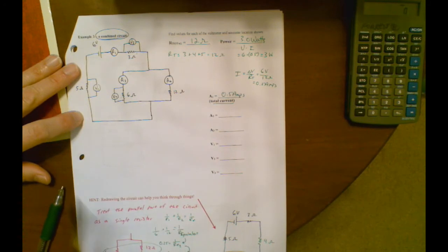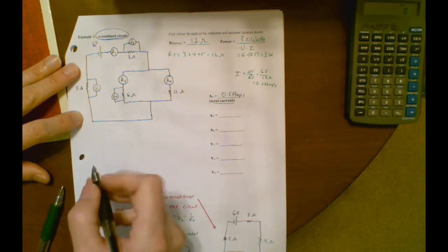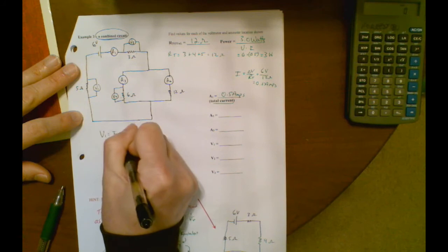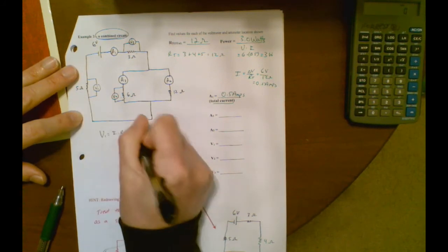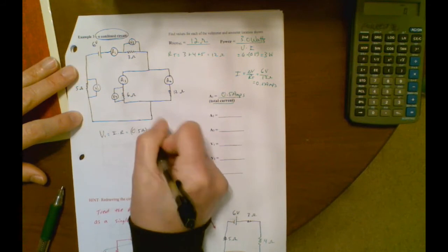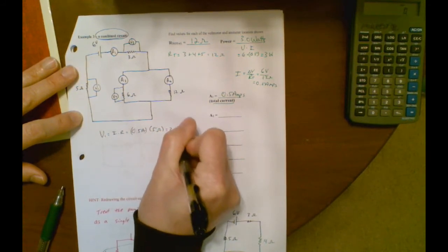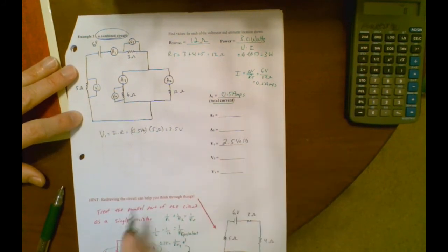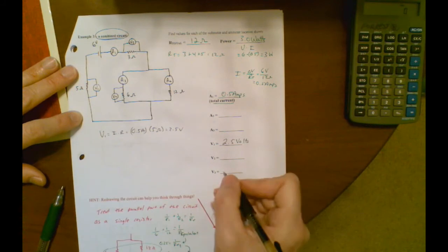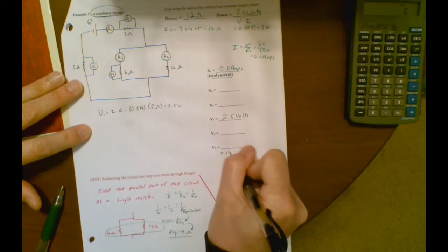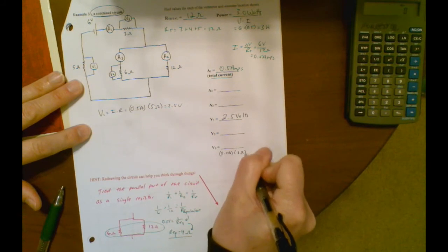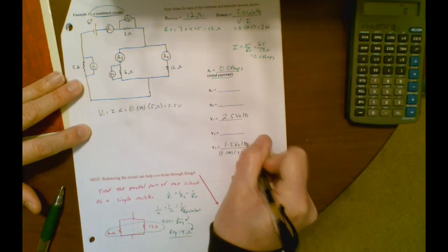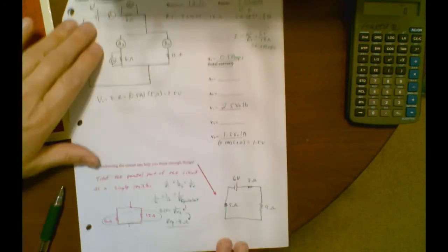Oh well. So if I know the total current in this circuit is 0.5 amps, I could say V1 is equal to I times R. Well, the current going through here is 0.5 amps. Resistance is 5 ohms. 2.5 volts. Now, thinking about the voltage here, I'm going to have for V3 0.5 amps, 3 ohms, 1.5 volts. Now there's a couple ways you can get V2, and we'll talk about it right now.